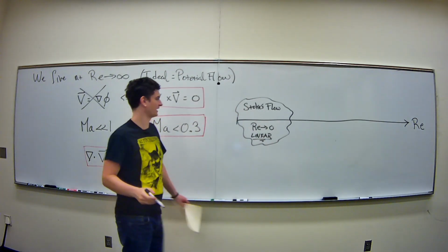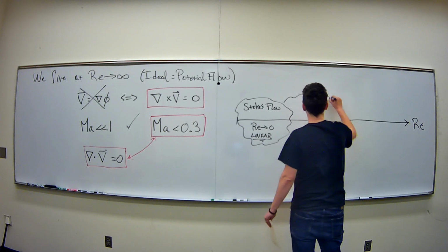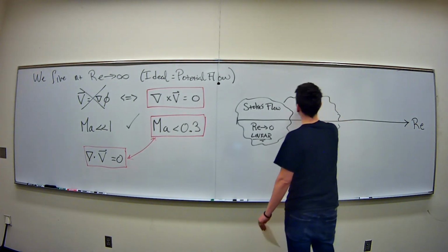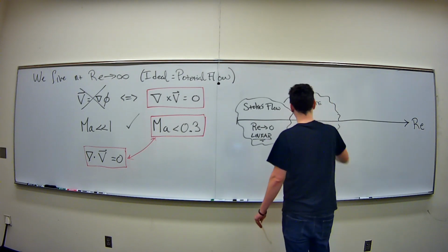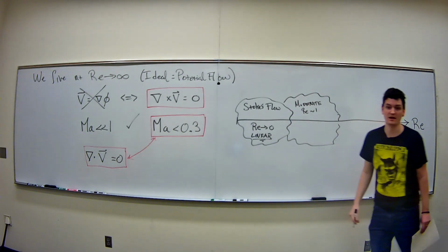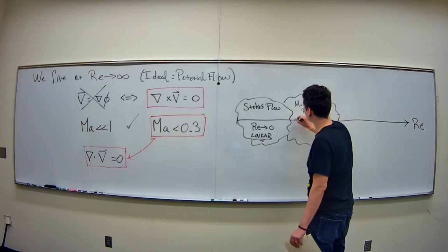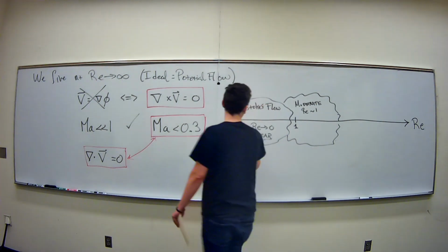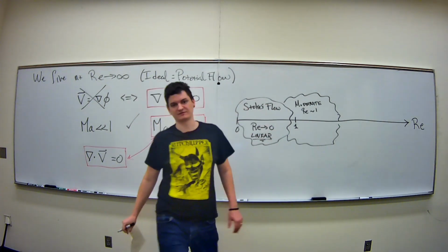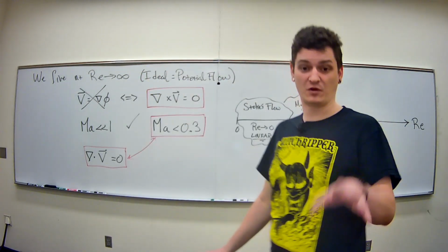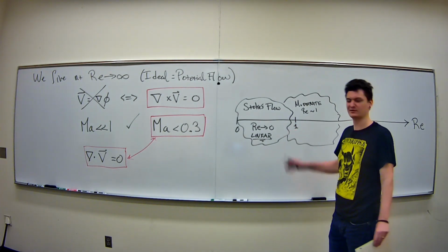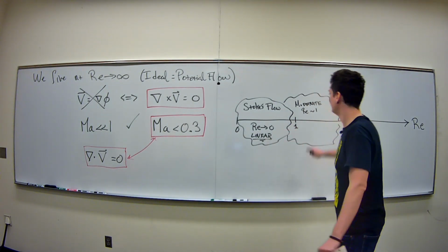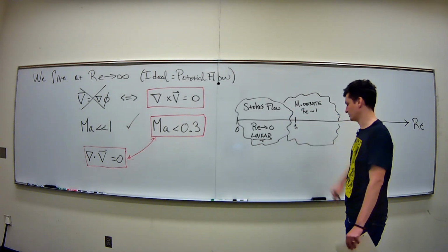which is very important. Okay, there's another part on this scale, and you could say moderate. Maybe you could even say around 1. So maybe 1 lives certainly in here, so I'll put 1 here, and this is 0. A lot of the relationships we had for Stokes flow even still work. That drag on a sphere, the 6 pi equation, that wonderful, nice relationship, is actually still within 10% if your Reynolds number is 1. Reynolds number being 1 is a pretty slow velocity. So these are still sort of creeping next to each other in the theory at least.